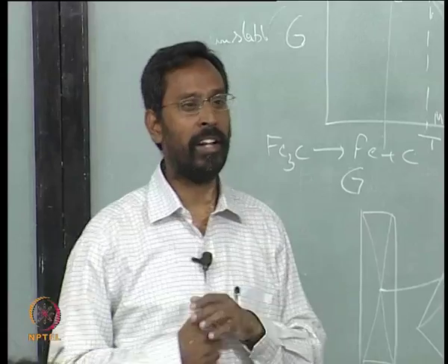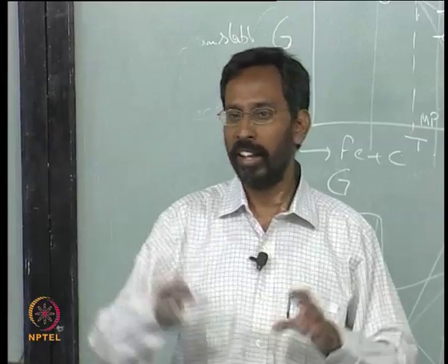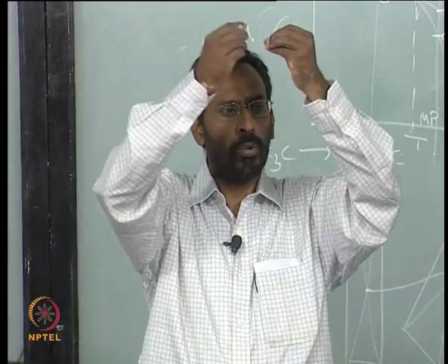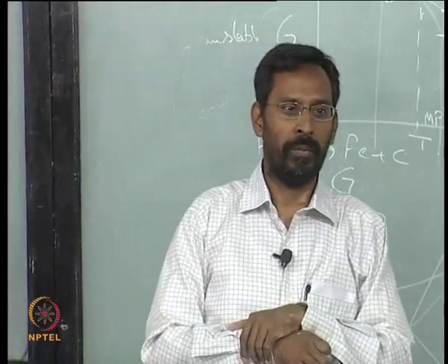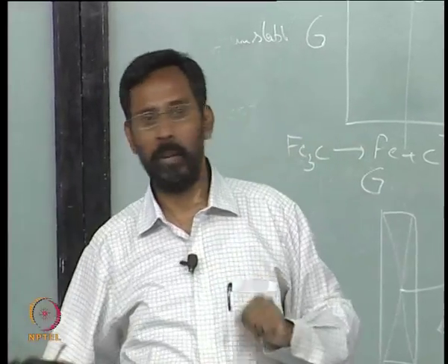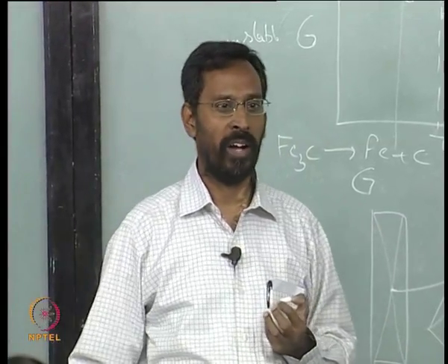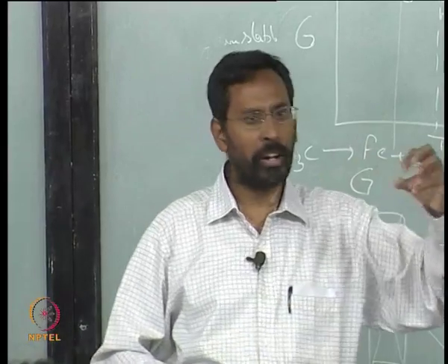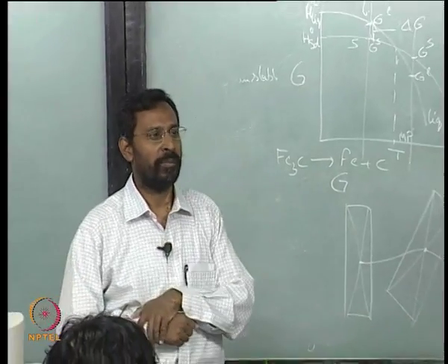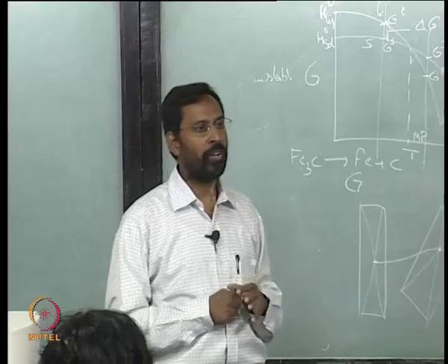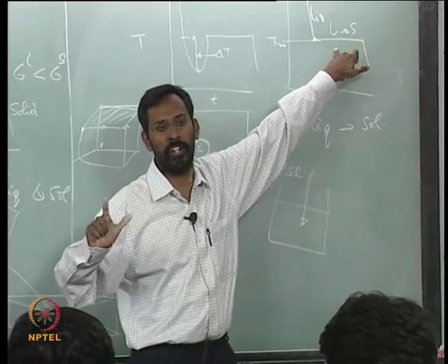And in fact, long back there is a great man by the name Turnbull who has done what is called droplet immersion technique. What he has done is he has taken a liquid metal, allowed it to go through a nozzle and made it into a stream of droplets, an emulsion of droplets by kind of atomization. When you do this, droplets of different sizes form, and the smaller droplets will have lesser number of heterogeneous nucleating sites, because people knew for quite some time that this kind of solidification is happening only because of heterogeneous nucleation.